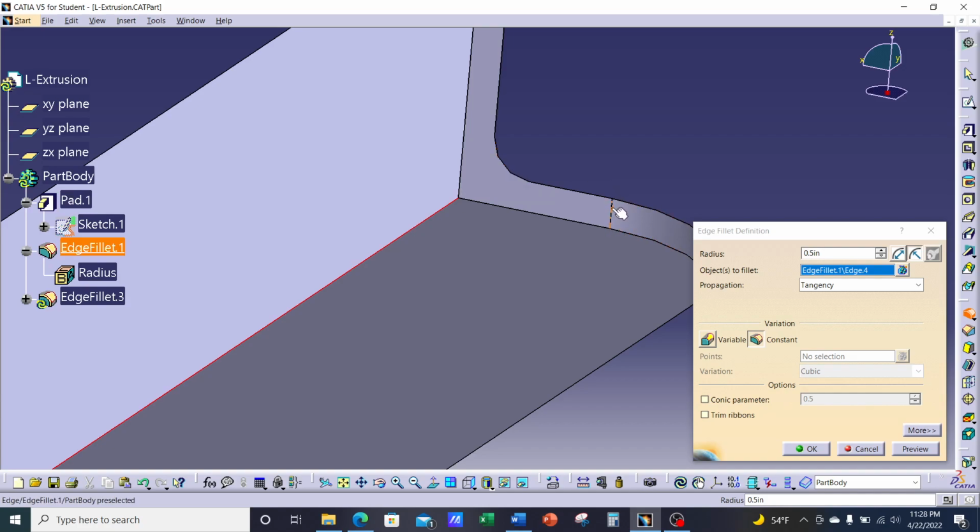So I'm going to take this thickness of 0.1 plus 0.125. So 0.1 plus 0.125, and I'm going to hit preview. And there it is. And the reason I chose 0.1 and 0.125, add them together, is to give us this constant thickness of 0.1 all the way throughout.